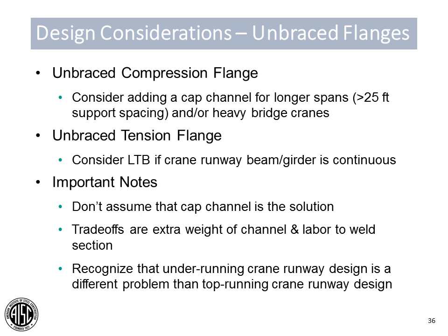Your stresses will transfer into compression stresses at those supports, so lateral torsional buckling does need to be considered. It's important to note that a cap channel is not always the solution. You'll hear me reiterate that a couple of times through this. There is a trade-off to the strength that you gain with these cap channels, in that you're adding extra weight to the channel as well as labor to weld those two sections together.